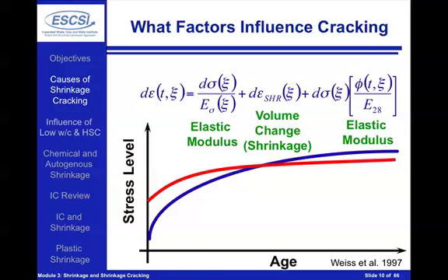What we can see here is the elastic modulus plays a large role in this problem. With a higher elastic modulus, actually leading to higher stresses developing in the system. What we'll see in Module 4 is that internally cured concrete will actually result in a lower modulus. It'll enable the concrete to be stretched over a longer distance, developing lower stresses in the overall system, and therefore the lower elastic modulus of the internally cured concrete is actually beneficial to help reducing the potential for cracking.